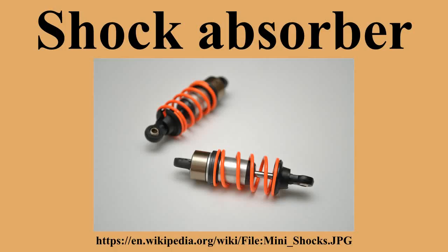Features and benefits. Some shock absorbers allow tuning of the ride via control of the valve by a manual adjustment provided at the shock absorber. In more expensive vehicles, the valves may be remotely adjustable, offering the driver control of the ride at will while the vehicle is operated. The ultimate control is provided by dynamic valve control via computer in response to sensors, giving both a smooth ride and a firm suspension when needed, which allows ride height adjustment or even ride height control, seen in some large trucks and luxury sedans, including Lincoln and Land Rover automobiles.